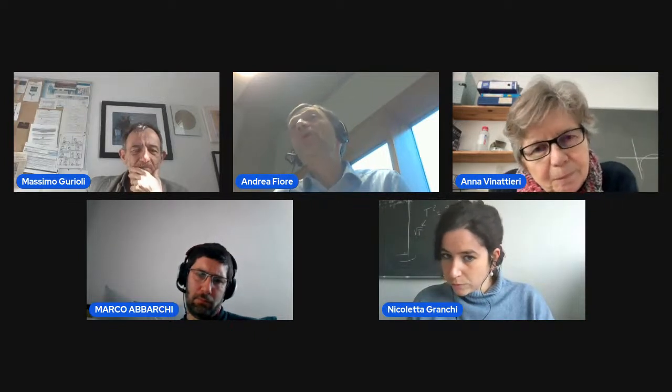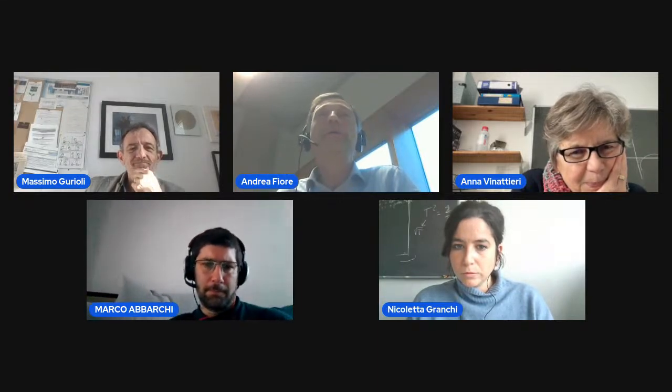That will apply also to silicon. Plus with silicon, I'm not sure you could do this trick either. You could think of going in the direction of gallium nitride. Then, of course, you can be transparent through the visible range, and other, more fancy materials. But yes, you can do this as long as you have a combination of an absorber and a transparent material in the wavelength, and a mirror, of course, in the wavelength of interest. For a different wavelength range, you could also use other approaches. In the visible, I want to mention there are companies which are offering multispectral arrays, and they are not monolithically integrated, I believe, so they are quite big, with much larger dimensions, but probably they still do the job.